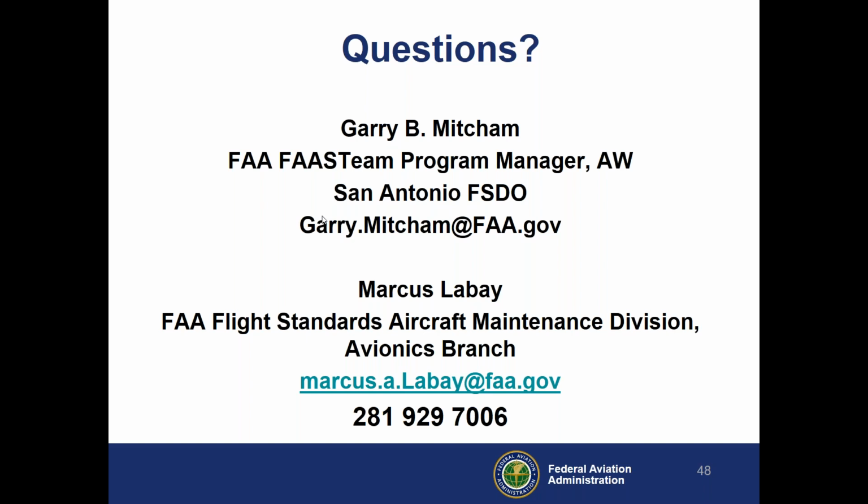Gary, I'll add to this. The message to the technicians and definitely to the management level that's overseeing training and such is that anytime there is a static test set connected to the aircraft and the aircraft static system is being told that the aircraft is at a different altitude than it's sitting at field elevation, they should be thinking about HMI.